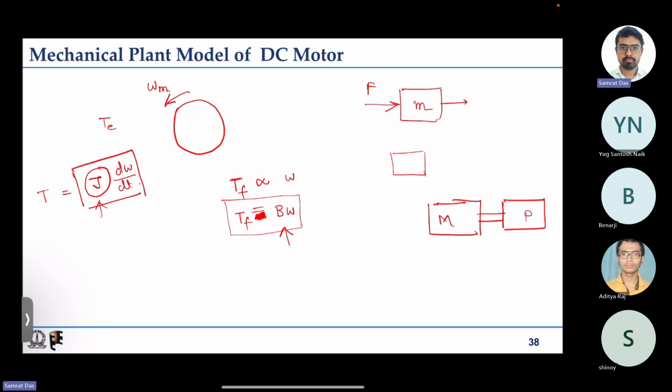Now whatever work the pump is doing, that will require some mechanical power. And if the motor is rotating at reasonably constant speed, then whatever power the pump requires divided by speed is basically the load torque the pump draws, or requires, from the motor. In the motoring action, this load torque also opposes the electromagnetic torque that makes the motor rotate.